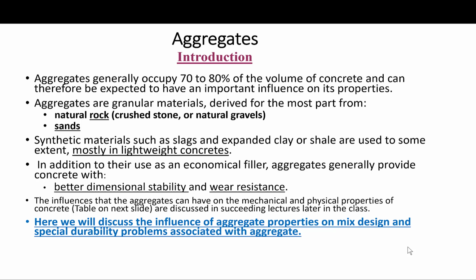In addition to their use as economic filler, aggregates generally provide concrete with better dimensional stability and wear resistance. Dimensional stability means volume changes. The influence that the aggregates can have on the mechanical and physical properties of the concrete are listed in the table I will show on the next slide.